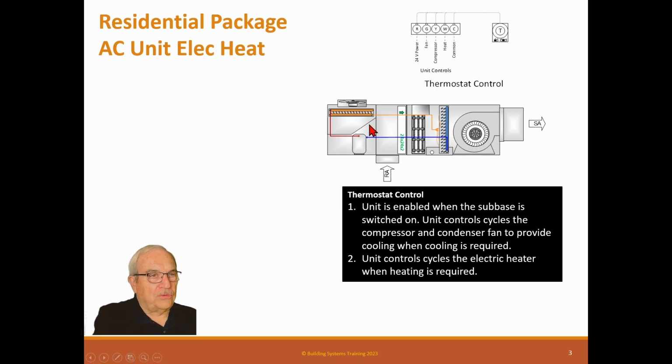The internal controls have all kinds of refrigerant safeties. They have low suction pressure, they have high pressure, and they have temperature of the gas. So there's certain things they watch and have logic in here to say, okay, we're going to damage the compressor, we're going to shut it off. So there are some things in here that this control system does that aren't overridden by the outside controller. And let me say, that's a good thing. You would not want a DDC control system that we've overlaid on here trying to run the safeties in this refrigerant circuit. That would not be a good thing.